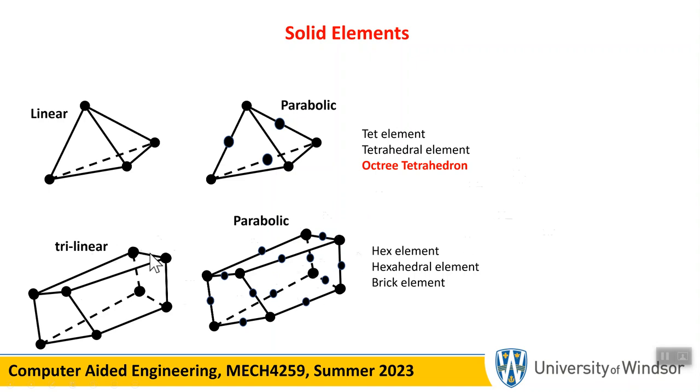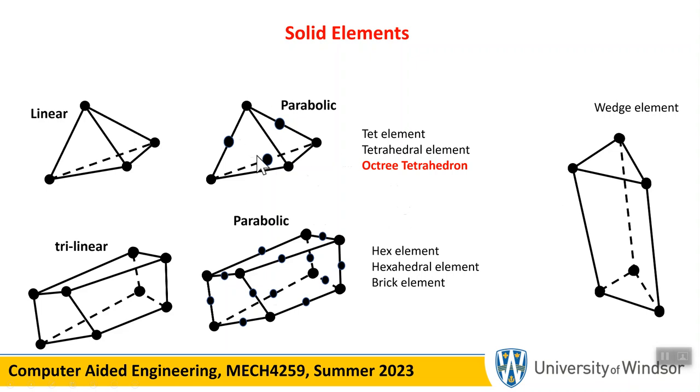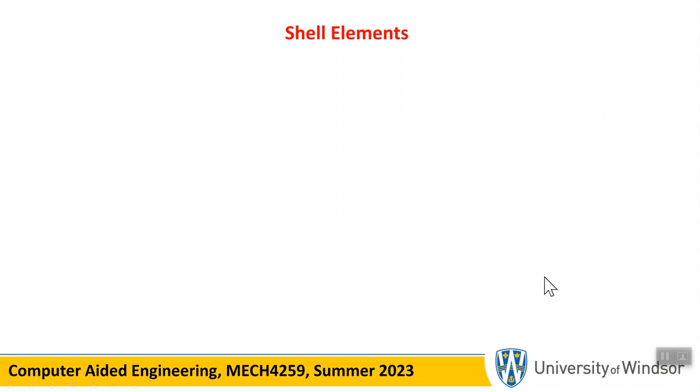Notice that these are 4-noded, these are 8-noded, these are 20-noded, I believe, and yes, we counted, it's going to be 20. I call it brick; hexahedral or hex elements, shoeboxes, these are all used in the literature. Now there is something in between these two, which are called wedge elements, by the way. These are also available in CATIA, but in the advanced meshing tool.